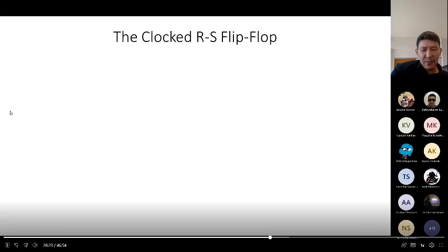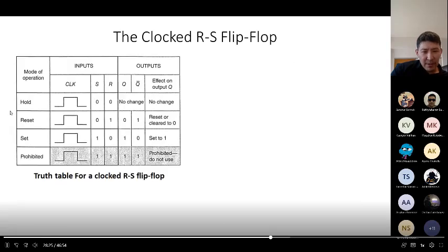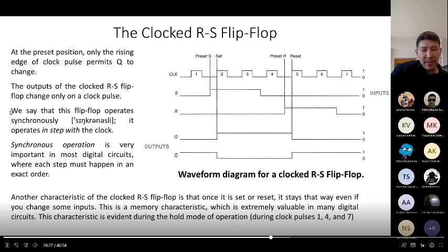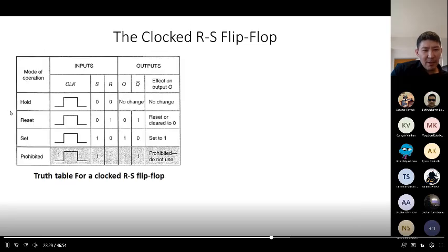So next, I think we need to consider the truth table. Here you can see the truth table for the previous clocked RS flip-flop. So actually, it shows the same thing as the waveform. So hold mode, you can see hold mode. When we apply 0, 0 to S and R inputs, the outputs will not change, they stay the same as before, so no change.